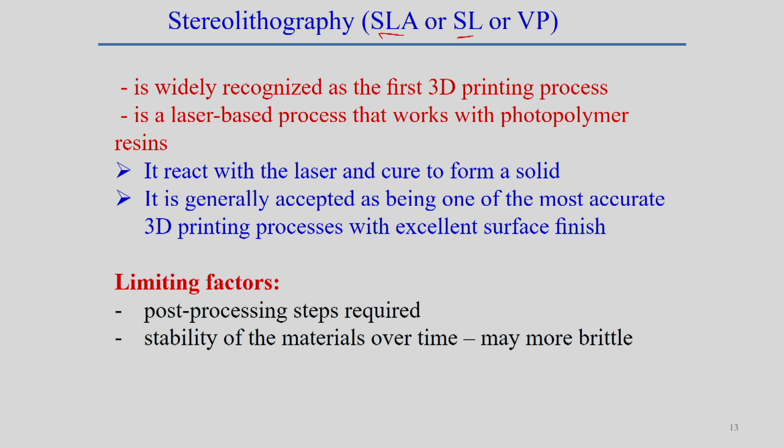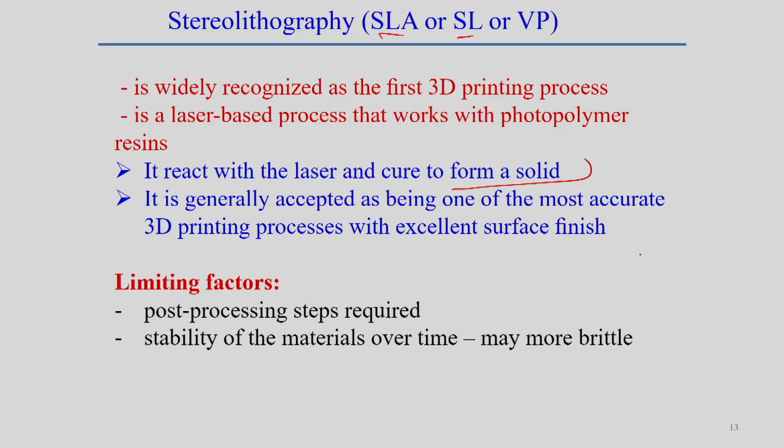Actually, when a laser is focused on the photopolymer resins, the resins react with the laser, cure, and form a solid. In a particular position, we can very precisely control the laser along its path. So only this path will solidify, that is, cure and form the solid. Therefore, according to this path, it is generally accepted as being one of the most accurate 3D printing processes